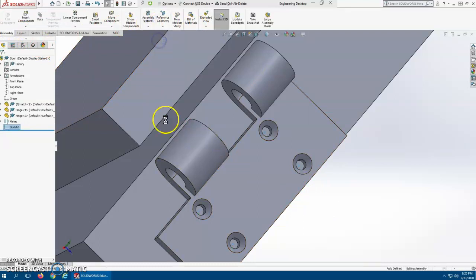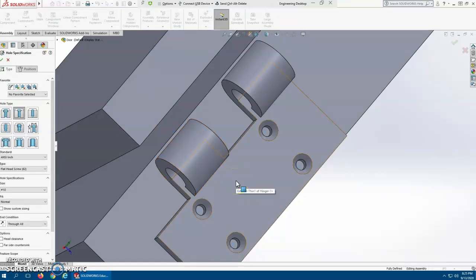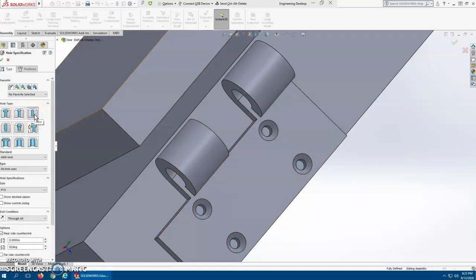I want hole wizard. We looked at hole wizard in the last chapter. So now what I want to do is put together some holes, and we're just going to go right here for our straight hole. We're going to drill it in for a hole. For size, we're going to use a 7/64 inch drill. Let's find our fraction. There's 13, 11, and 9/64 is getting closer. 7/64 drill. And we're going to want to drill that.